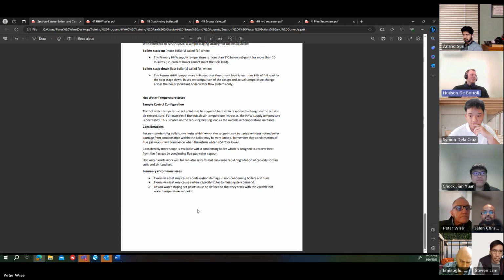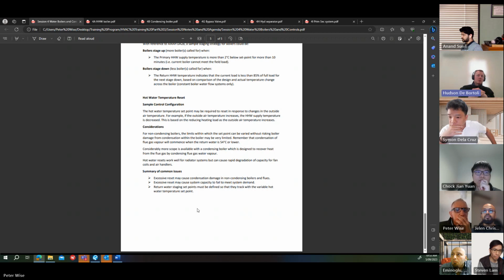Yeah, I've got a quick question about the bypass pressure drop. So is the reason behind trying to make sure that pressure drop is equivalent or thereabouts to the field, is that to do with sort of valve authority? Not really. No, it's about making sure that the control valve can handle the full flow of the water.